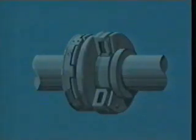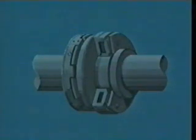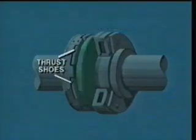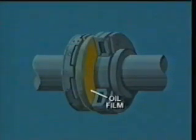To control the axial motion of the shaft, thrust bearings are used. They are usually of the double-acting tilt pad design, so that thrust loading in either direction can be supported. A typical thrust bearing has a thrust collar attached to the shaft and thrust shoes arranged in a circular bearing case. Between the thrust collar and thrust shoes, an oil film is used to support the thrust load.